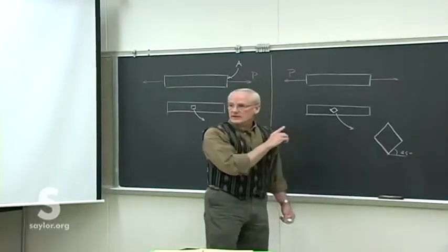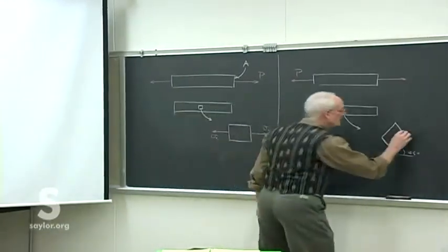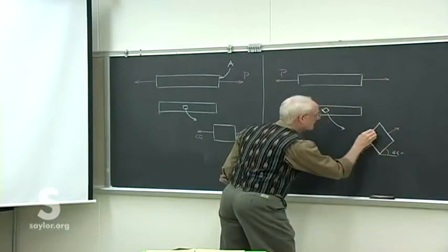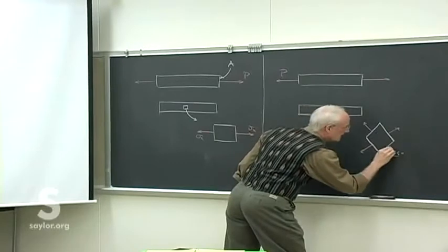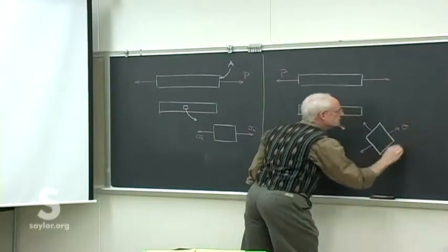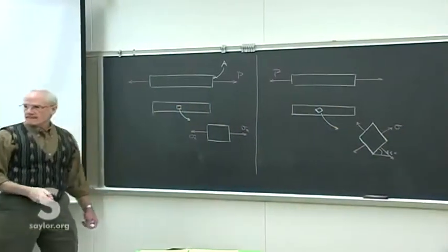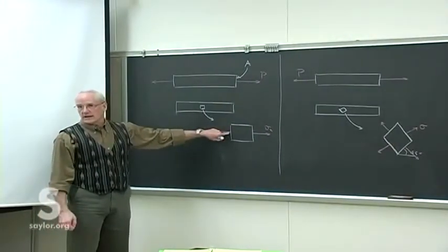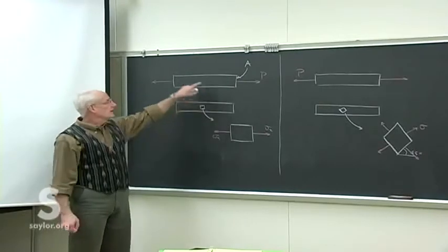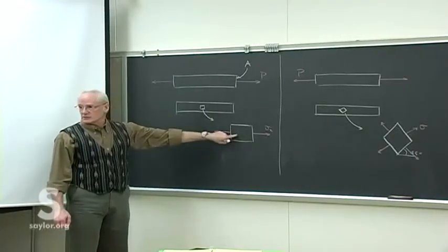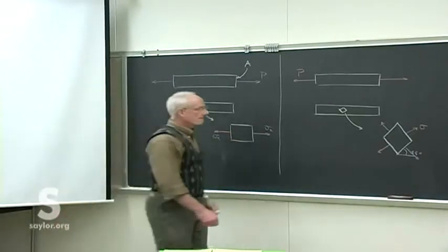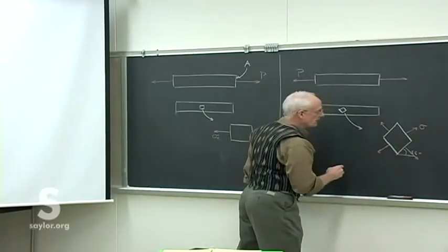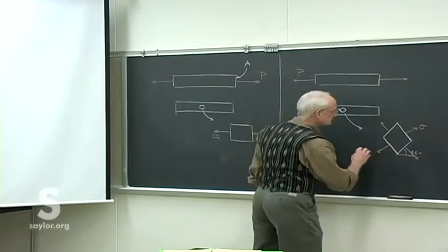I know from the oblique plane study we did to open class that I have normal stresses on all of the faces now. Before I only had them on one. I only had an axial force on the member. I'm only going to have axial forces in resultant. But when we took a side look at these, we got extra components on the other faces.